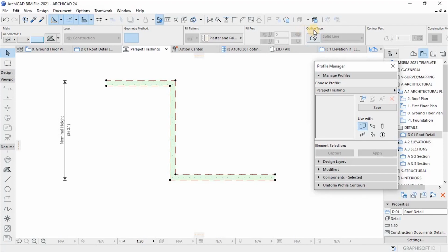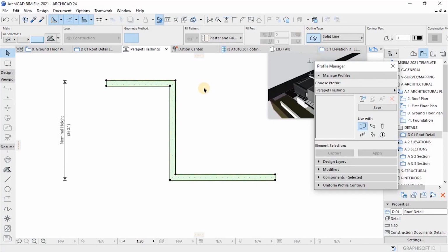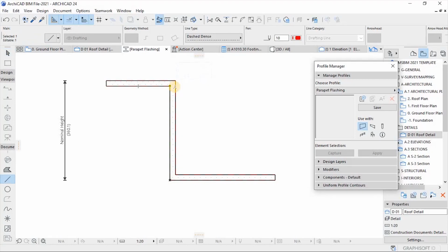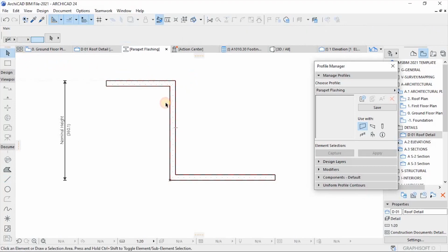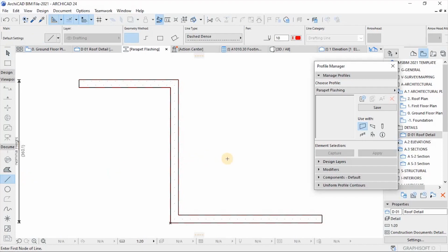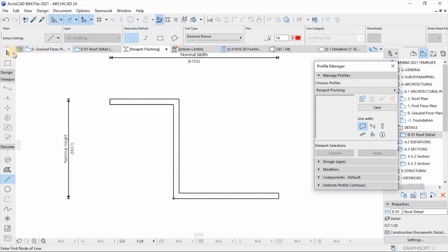And then go to outline, activate the outline so that you can see. I can now get rid of the 2D lines. To select them all, you can select the line tool and then hit Control A to select all, then delete to remain with the fill.